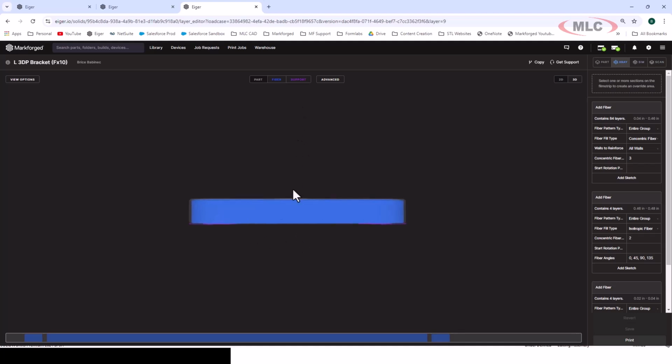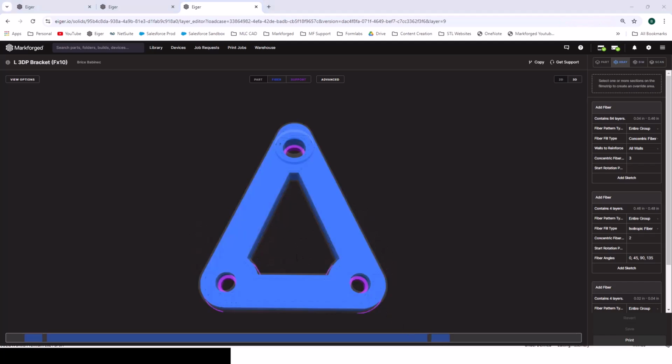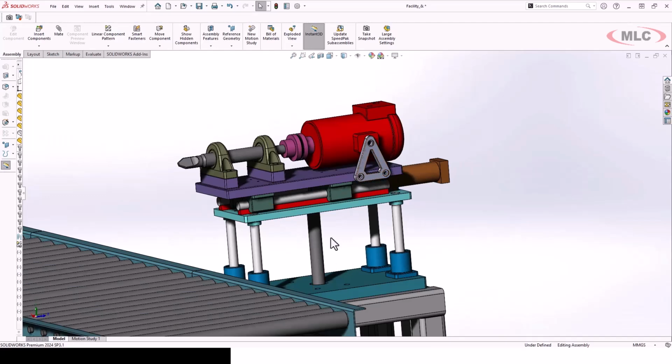And so those sandwich panels are going to fight forces that are coming in perpendicular to this part. And the reason they're on the outsides is because that's where you're going to have your highest tension and compression for this type of force. But in our case with this part, if we look back at our model here, there's not really any force coming in straight at this bracket. It's all going to be as this bit is being pushed into a part on the line here, it's going to be resisting and pushing the bracket sort of off to the right-hand side this way.